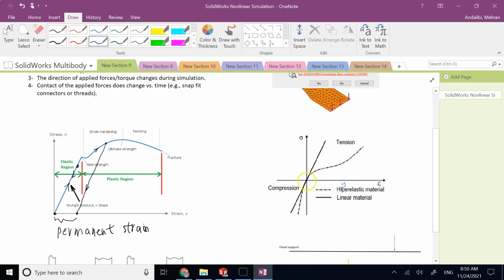But if I start from zero stress, zero strain, and go up the curve, and I come here, right? So I follow this path, and I end up here. Now, if I let go of the force, the stress has to go back. So I should definitely end up on the epsilon line, but where?